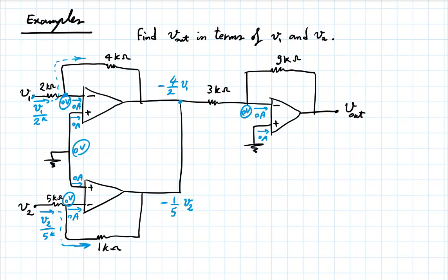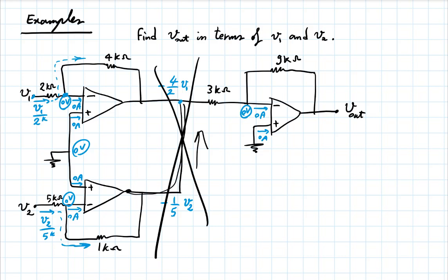And so did the bottom left portion of the circuit. And if you connect two things that act independently, but at the end you take their outputs and connect them together, it is not any better than taking two voltage sources and connecting them together, right? So very bad thing to do here, okay? You can't really solve this because you shouldn't build this circuit to begin with. I mean, the answer is that yes, in this wire, like you said, there would be infinite current. Now, maybe that infinite current runs from this point all the way to this point, or anyway, something very bad.